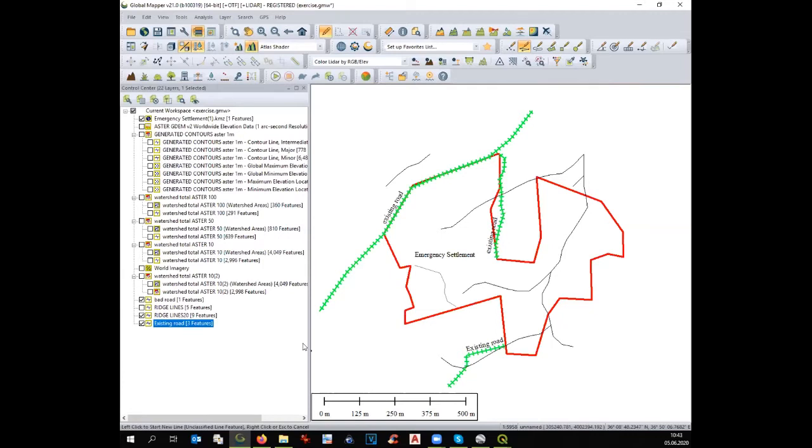There are advantages and disadvantages. I prefer to do it in GIS, but GIS is not a precise software. So what I do, I draw the community precisely in AutoCAD, millimeter precise. I draw the tents precisely in AutoCAD, and then I import the precise drawing into Quantum GIS.